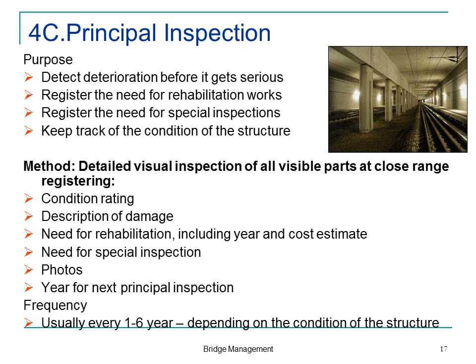The principal inspection is something we more or less only do when it's required. Some countries specify by law that it has to be done so and so often, but we say it should be between every year and every 6th year, depending on the condition of the structure. And the purpose is really to detect the deterioration before it gets really serious.